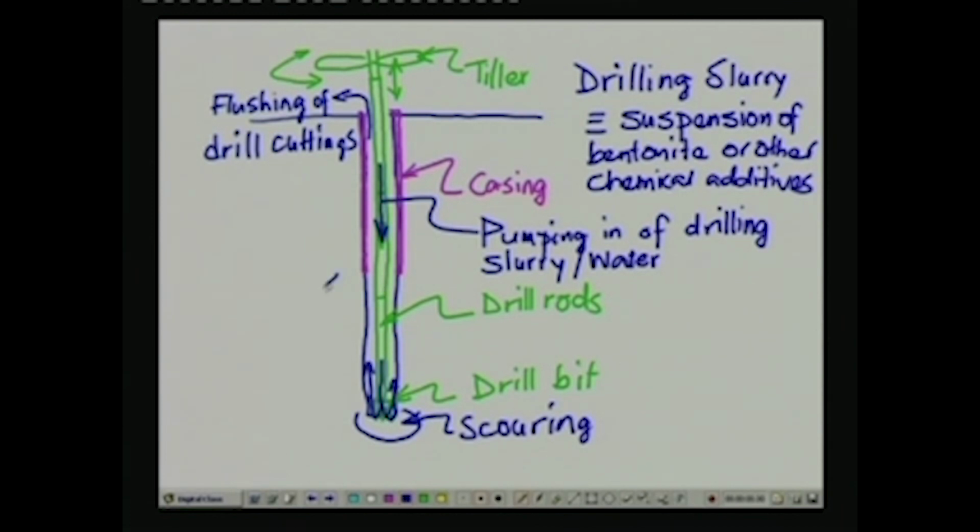Now, drilling mud also has got another function. You can see that the bottom portion of the holes are typically left uncased. So, drilling mud actually stabilizes the uncased portion of the borehole by preventing the soil within the uncased portion from collapsing into the borehole once the support is removed by the drilling process. So, that in a sense is the technique of washboring.